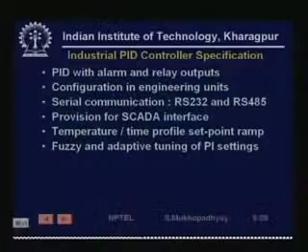Incidentally, the heat transfer coefficient tends to change because in the pipes you get depositions from seawater. So, in such cases, for efficient response as well as for things like energy efficiency, you need to tune PID controllers from time to time, and so they have provided algorithms for doing that using fuzzy; fuzzy means there is a special technique called fuzzy set theory, which is used to design controllers.